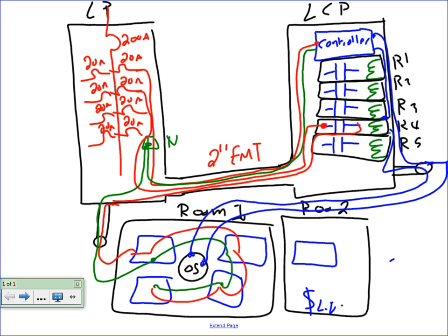Perfect. So now when the occupancy sensor senses that somebody's moving, it closes the contact. That contact brings a signal to the controller. The controller closes in its part, closes a contact and brings a 24. This is 24 volt, by the way. This is 120/24 volt. So it will bring a 24 volt across this coil. This is 24 volt. Everybody can see that 24 volt. I brought 24 volt across this coil. What happens when you bring a voltage across a coil that the coil is rated for that voltage? Slam, shot. Now my lights are on.